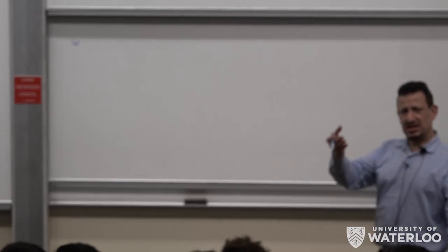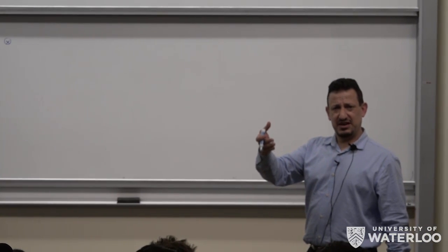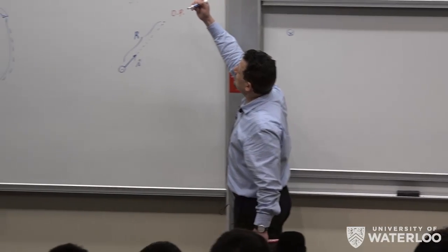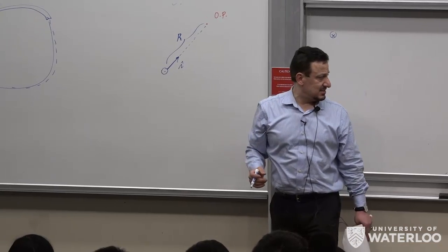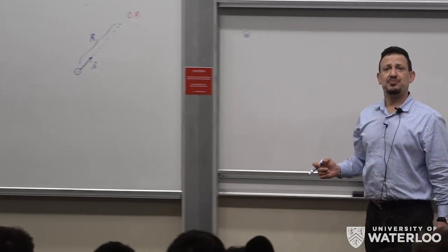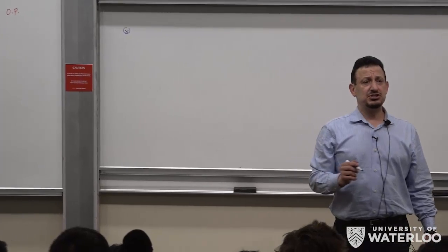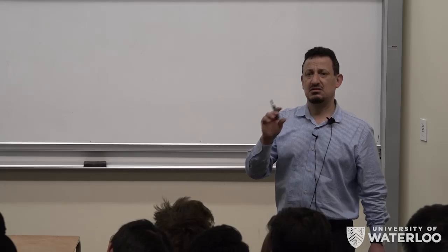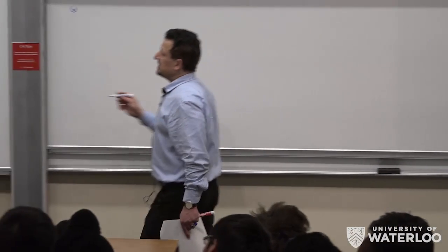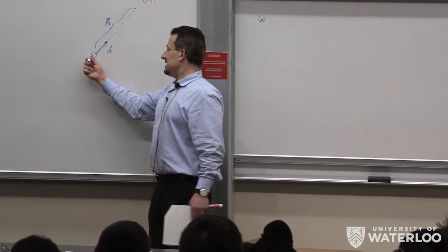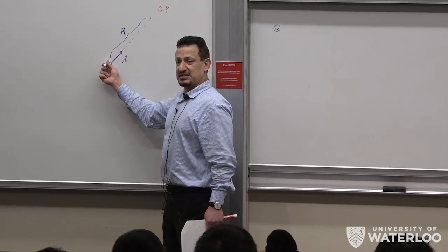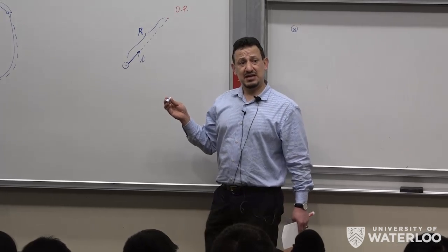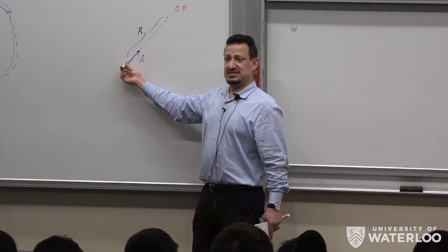What else is there to decipher? That's all. I need to know I dL. It has a value, it has a direction, and I need to know R. So the rest is I need to perform the cross product, I dL cross R. Some books, to differentiate multiplication with a cross, put the cross in bold, thick font. So I need to know the plane. So I dL is going in that direction. So the first thing I need to determine is the plane that has the R and the I dL.